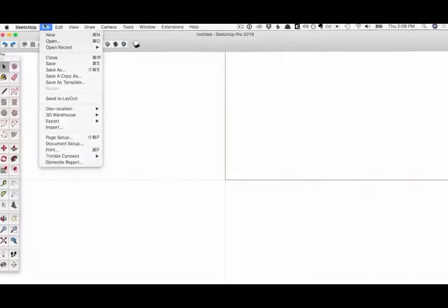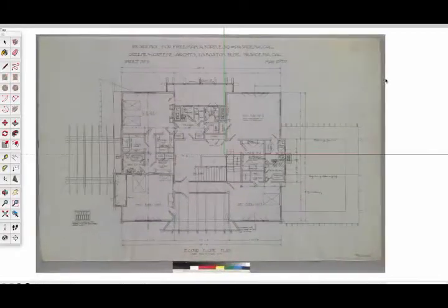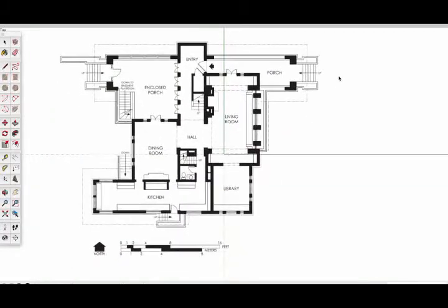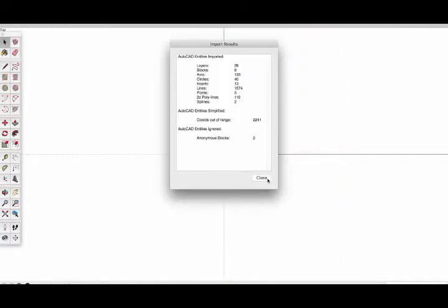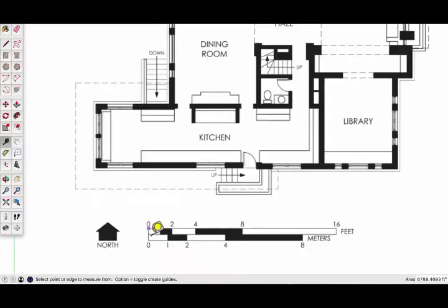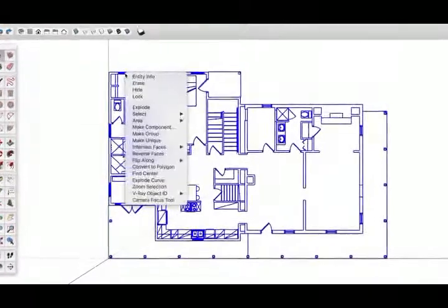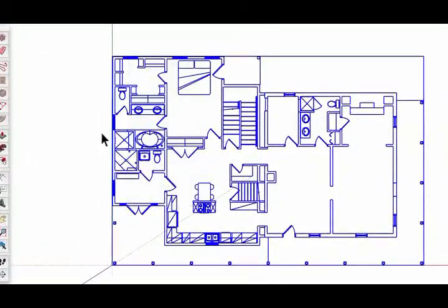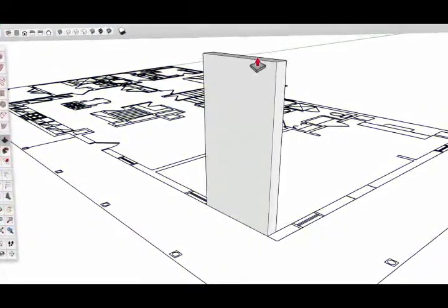And even better, you can make sure they come in at the right scale so your SketchUp model is dead accurate. Here's how. In your top menu, you can choose to import an image of a sketch or other drawing, a PDF of a floor plan or technical drawing, or a DWG or DXF if you're starting from a CAD file. After importing an image or a PDF, you'll need to scale it. With CAD files, they come in at the right scale, but you do need to be sure to turn them into a group if they aren't already. Then, you can use your imported file as a reference as you model right on top of it. So that's the importing feature in SketchUp Pro.